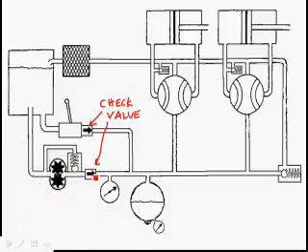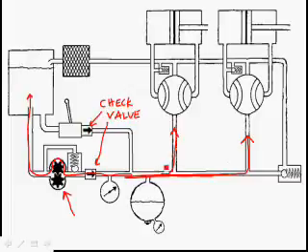the check valve is set up so that, let's just say the engine-driven pump breaks and it stops spinning because it's broken. We want to keep the pressure in here so we can use it to go through the selector valves and run our actuators. But if the fluid could run through past the pump and go back to the reservoir, then the pressure in here would go down.